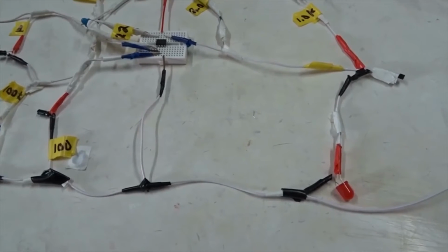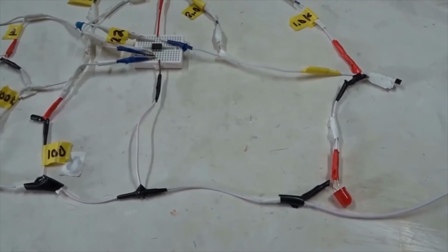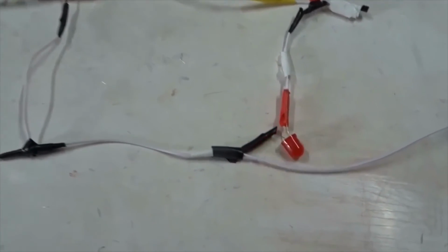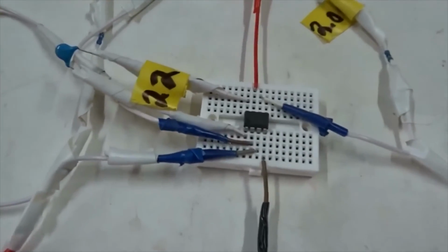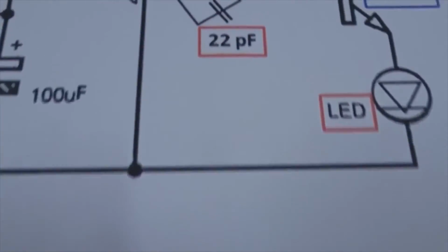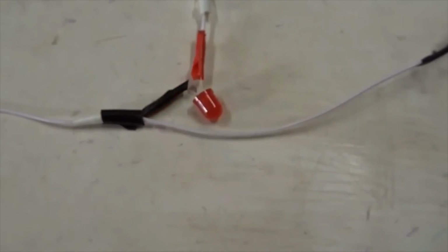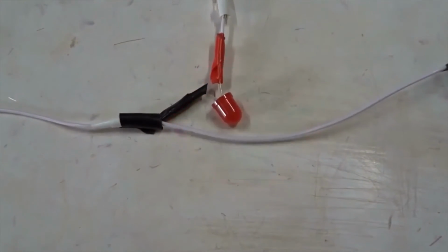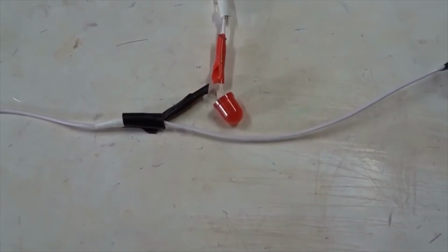Watch as I turn the voltage up slightly to 6.5 volts. This LED starts strobing. It all depends on putting a capacitor here, 22 picofarads, between outputs 1 and 8 to trigger the strobe. You just change the voltage very slightly. The strobe can go on or off, like 6.3 to 6.5.